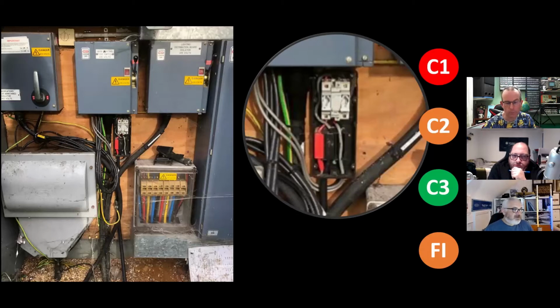But again, you look at why is there no metering, the bending radius of the cables, the space and clearance around the cutout to enable it to be accessed and maintained. I see so many bending radii now that are just... I mean, it's as if electricians seem to have forgotten. Bonner's highlighted a good thing: reduction of CSA in that joint box, the red, yellow, blues. That is ridiculous. It's similar to the one we found the other day on the PV, where you had the 6 mils in the comb trunking jointing onto like 70s and 90s, and it just made no sense.